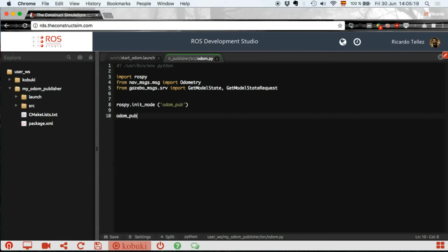I'm calling it odom_pub, with rospy.Publisher, and we need to specify the name of the topic. I'm going to call it my_odom, for example. And the type of messages, of course, has to be Odometry.